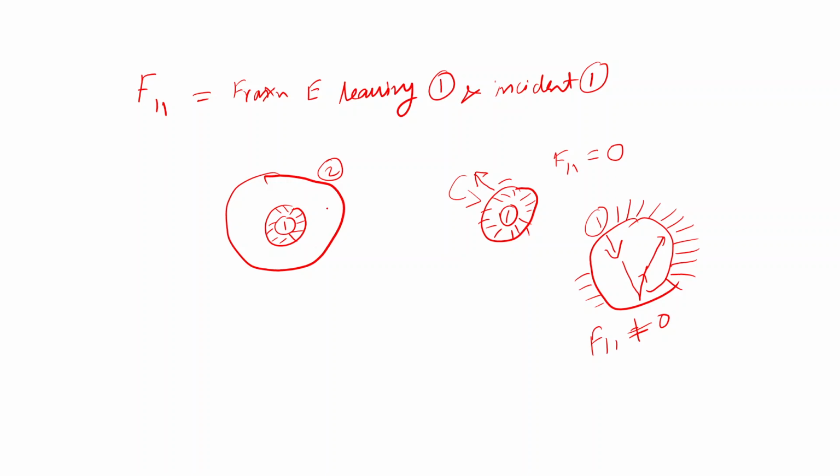In this specific question, the outer surface was reflecting, hence the radiation which has left the first surface won't come back to this surface if we consider only this object. That is why we take F11 as 0, whereas for the second object the outer surface was coated and the inner surface is reflective, and that means F22 was not equal to 0. So while calculating F11 and F22, you have to consider only that specific surface or object.